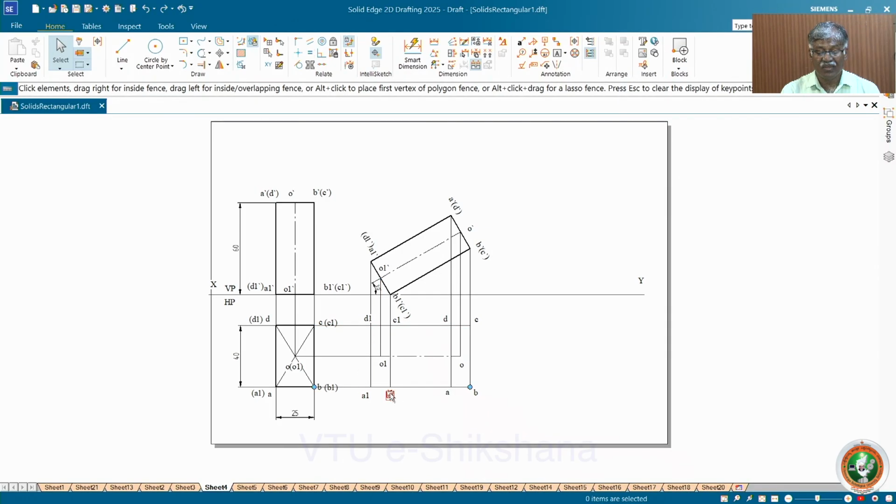Out of this, only B1 C1 is left, that is out of the boundary line. That must be considered as the hidden line because the base is not visible here. So invisible surface edges other than boundary lines are dotted. Yes. Then no crossing line and base because you have only the boundary and these two rectangles, that's all.